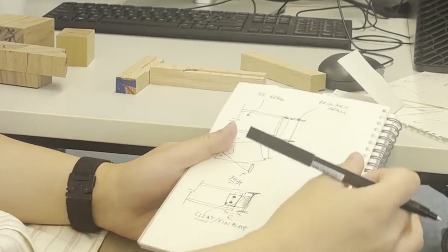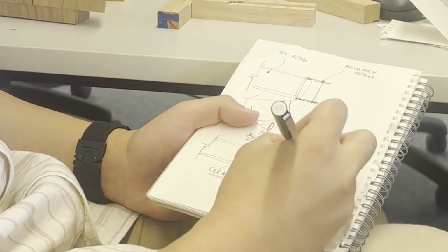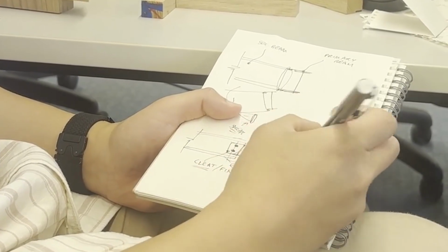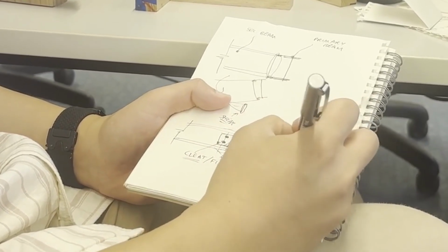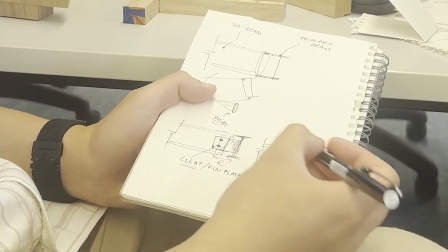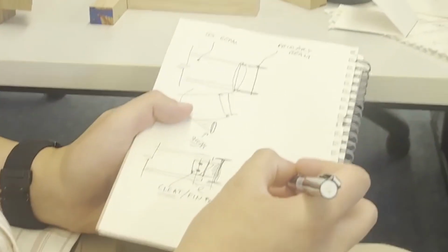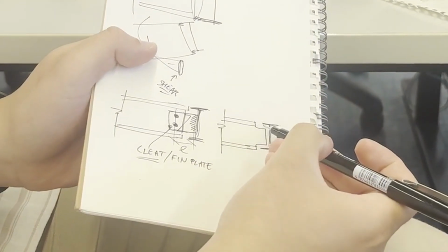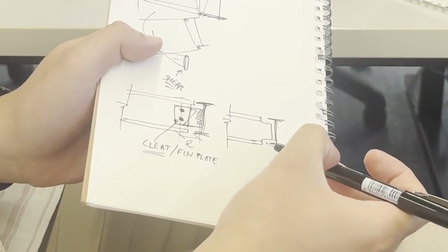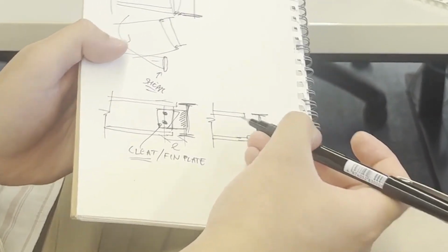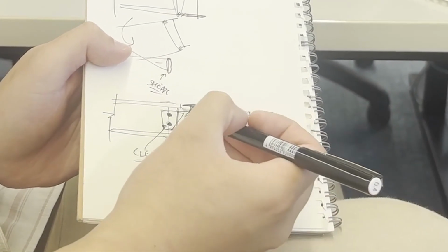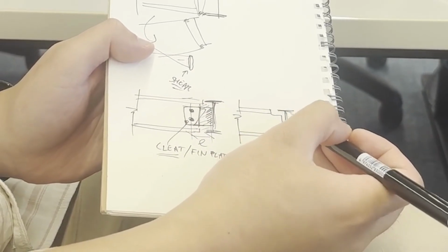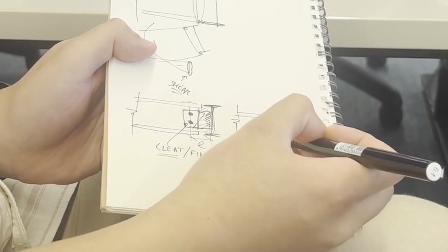The more optimal design, and what you'll see a lot in industry practice, is something pretty close, but they do something called coping the flanges. So now they've just cut off the flanges of part of the universal beam, and instead of this big gap between the two beams, now the web of the beam is close to the web of this beam, and you do the same cleat connection.